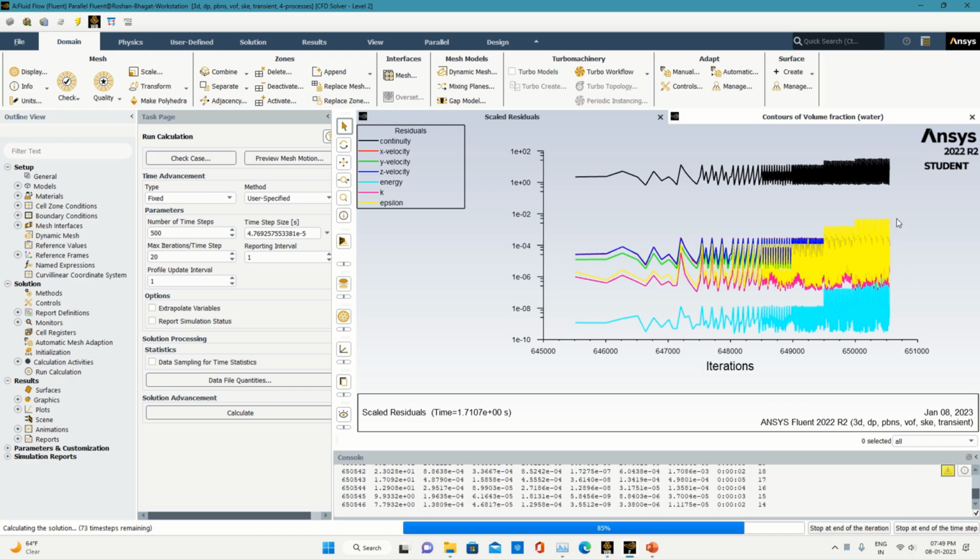We are not observing the problem of Courant number, though there was an issue with the Courant number, that is the floating point exception error in between, but successfully we managed by changing the time step, as well as closing the Fluent setup, and then again proceeding with the simulation. So now it is working correctly, and we expect to reach quite near 33,000 time steps, and it will go up to 50,000 time steps to visualize things in a better way.